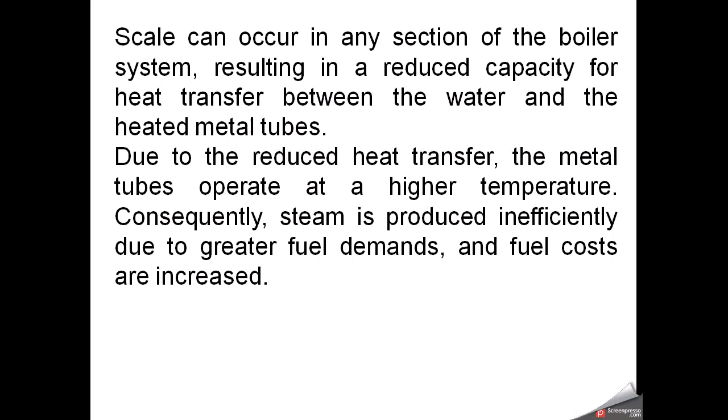it reduces the capacity of heat transfer from the heat source to water through these metal pipes. Due to reduced heat transfer, the metal tubes operate at high temperature, because the scaling has occurred on the water side, so there is less cooling, less heat taken away from the furnace to the water.